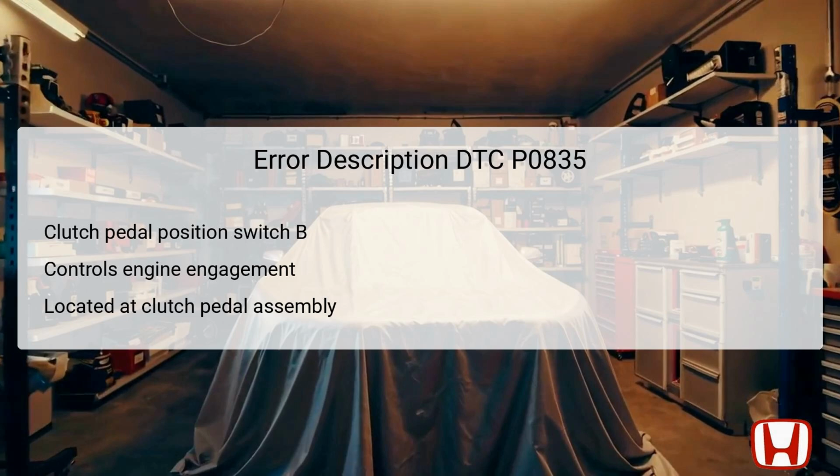If the switch indicates a low voltage condition, it can prevent smooth engagement or disengagement of the clutch, complicating the driving experience. As such, accurate diagnostics and repairs of this circuit are necessary for optimal performance. When diagnosing issues, the technician typically checks this component through the Honda Diagnostic System, HDS, tool, verifying its status through data lists and error codes to pinpoint the malfunction accurately.